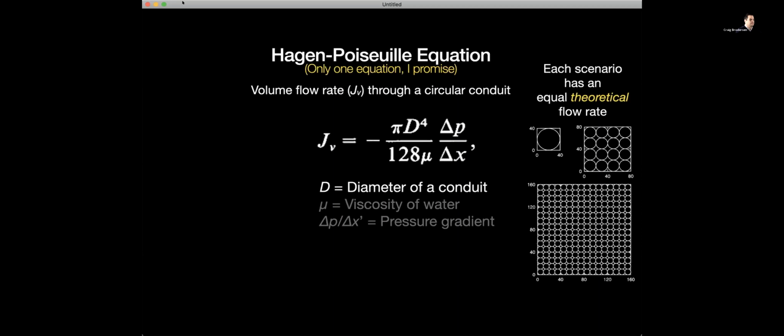The idea here is that we've been measuring hydraulic conductivity through stems by attaching them to a hydraulic apparatus and then pushing water through them. And then we can also figure out how good a job this equation does at approximating the flow rate through a stem, through these essentially circular pipes.